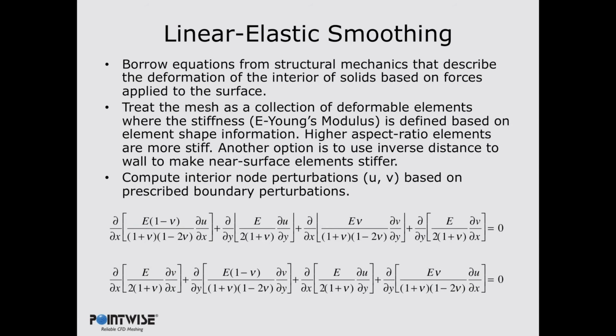The next few methods were performed by summer interns here at Pointwise, students that were my students at University of Tennessee. The first one is going to use linear elastic smoothing. This is a common method used in moving meshes. You borrow the equations from structural mechanics that describe the deformation of interiors of solids based on forces applied to the surface.